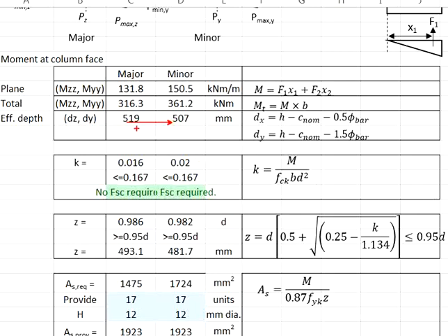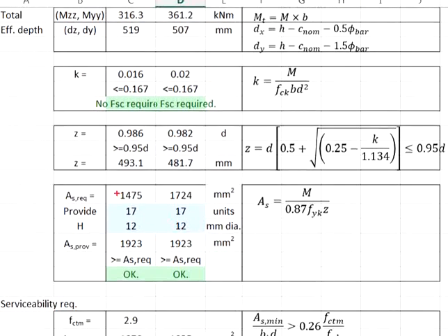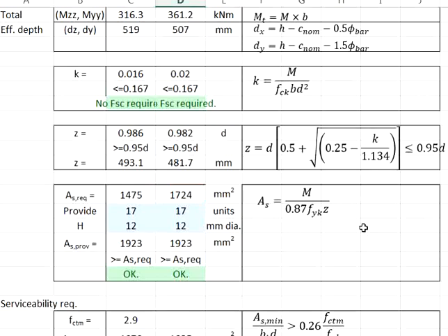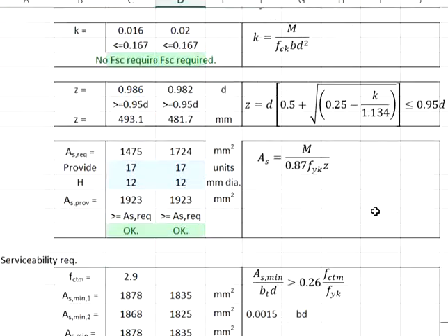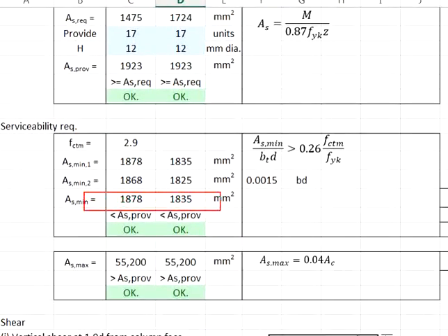When these two effective depths swap, the amount of reinforcement required in the major axis will increase slightly, and the amount of reinforcement in the minor axis will reduce slightly. This might lead to a slight saving in the amount of reinforcement bar, provided that they fulfill the minimum As.